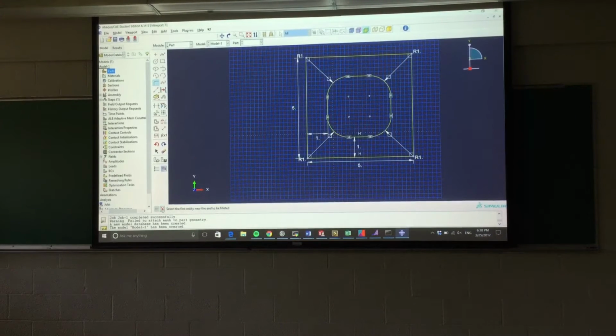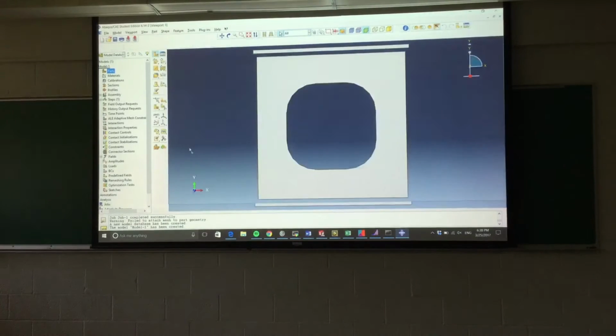So the reason why we're not going to fillet the top left edge is because that's not where the max stress concentration occurs. So it's really not a factor in this simulation, and it also would affect the loading condition as well, because the top surface geometry would be changed slightly. So it's just more convenient to keep that edge not filleted. So just click escape and done, and we've created our part.